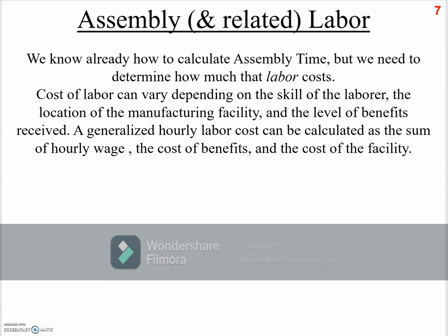So assembly and the related labor. We already know how to calculate assembly time, but we need to determine how much that labor costs. The cost of labor can vary depending on the skill of the labor, the location of the manufacturing facility, and the level of benefits received. A generalized hourly labor cost can be calculated as the sum of hourly wage, the cost of benefits, and the cost of the facility.